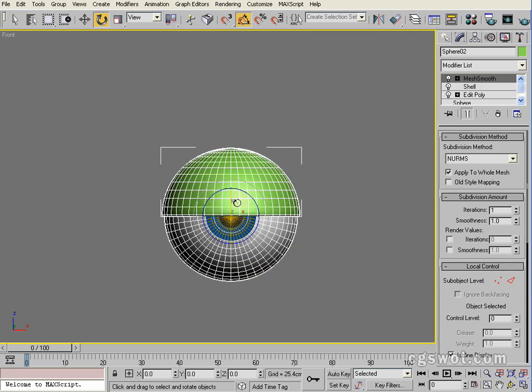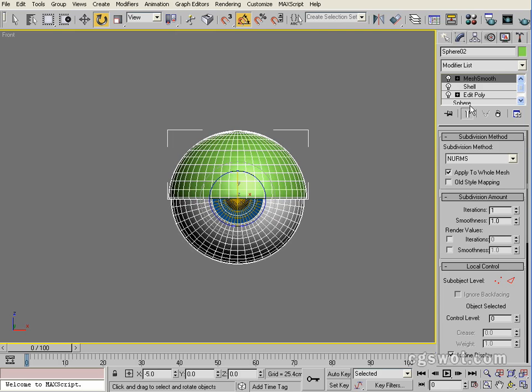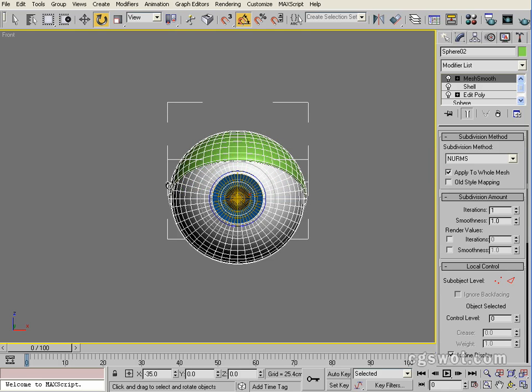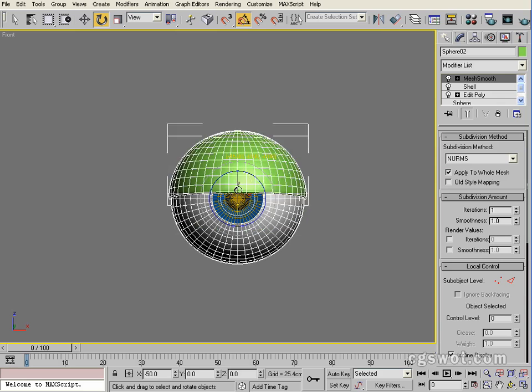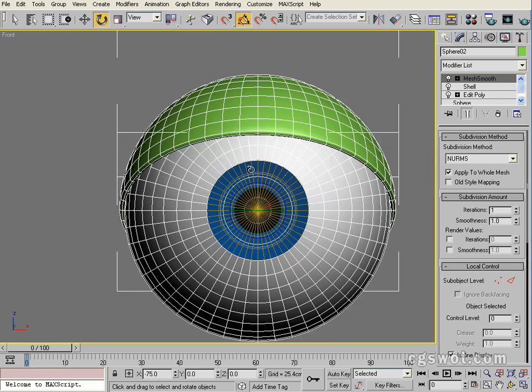And the beauty of this system too is that if we were to just animate, which some people tend to do, I don't particularly like it. Some people will go to the sphere hemisphere setting we set to 0.5, and then they wire that setting to a controller for blink controls. But what that actually does is cause a flat, flush eyelid line that comes straight down the surface of the eyelid. But what we've got here, as we go up, it causes a curve, and as it comes down, it causes an opposite curve, and that's a lot more accurate. I think it looks a lot more natural.